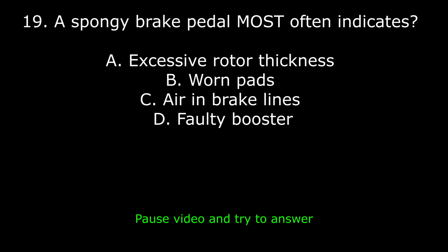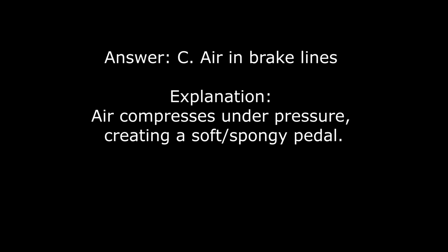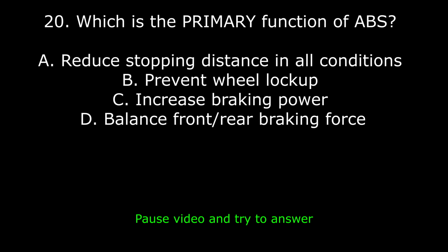19. A spongy brake pedal most often indicates A. Excessive rotor thickness. B. Worn pads. C. Air in brake lines. D. Faulty booster. Answer. C. Air in brake lines. Explanation. Air compresses under pressure, creating a soft, spongy pedal.